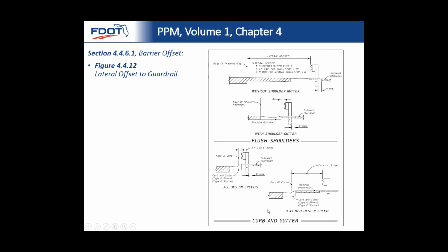For the curb and gutter installations, like I mentioned, for all design speeds with a curb, the preferred installation is the 5 inches from the face, which is how it's worded in the criteria. It can still be located at the face if we have really restricted criteria, which is why we mentioned the 0 inches here still. Just the preferred application will be the 5-inch offset.